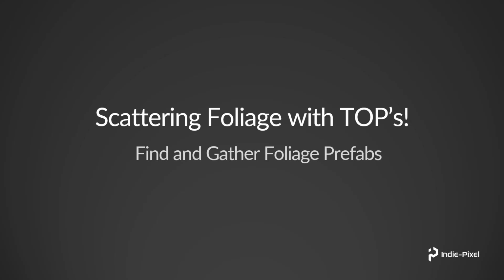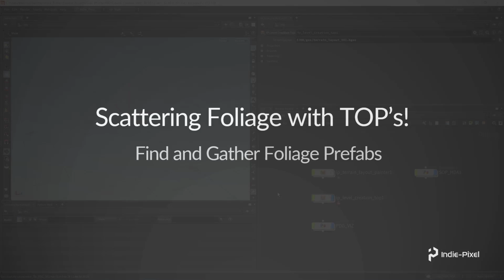Okay, so the first step in this process to go and gather all of our foliage prefabs is to set up a couple of file pattern nodes inside of our top network. And then what we want to do is merge them all together and put them into a single partition so we can work on all the files all at once. Okay, so let's take a look at how that is done inside of Houdini.